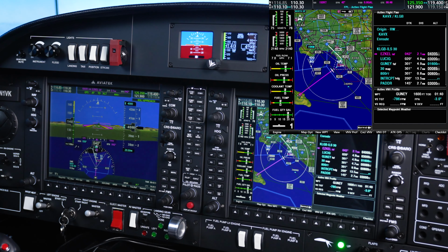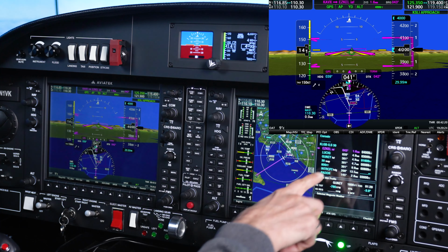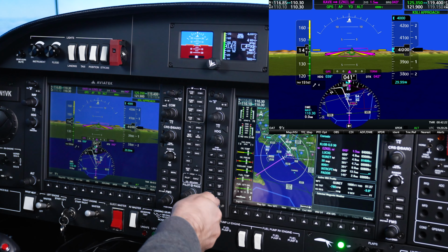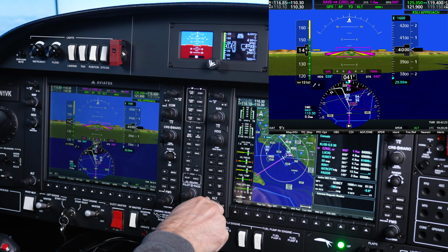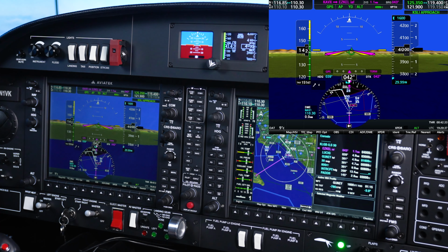It automatically calculated our top of descent. So let's say the approach already cleared us for the approach. So what we can do now, we can pre-select our final approach fix altitude of 1600 feet, arm the VNAV, so we can see we have the VPath armed. Always everything which is armed is white, and currently engaged is in green here on this scoreboard.